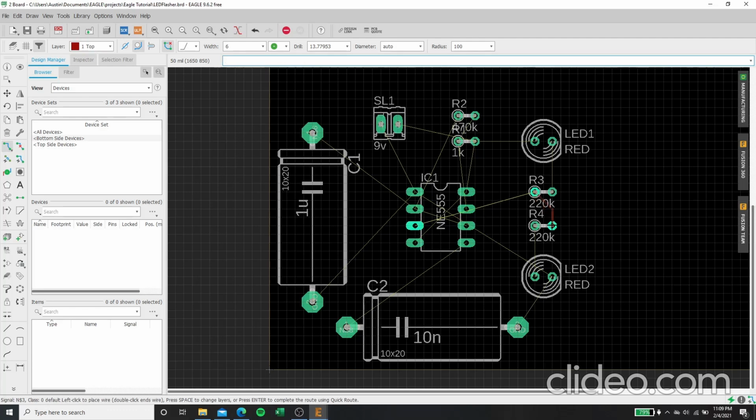And so you click on the part where you want to lay down your trace, and you can see I replaced that yellow air wire that was right there with a red trace. And so you can do these for all the different parts, and this is something that you're just going to have to play around with. But I can switch between laying down red traces to laying down a blue trace by hitting the space bar. And so now I'm connecting on the bottom of the board.